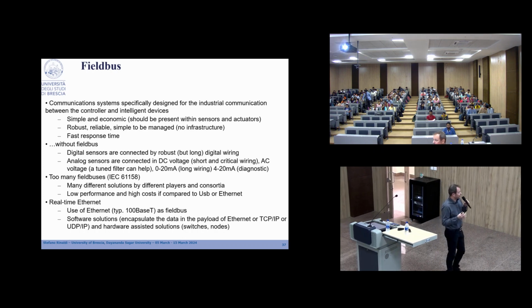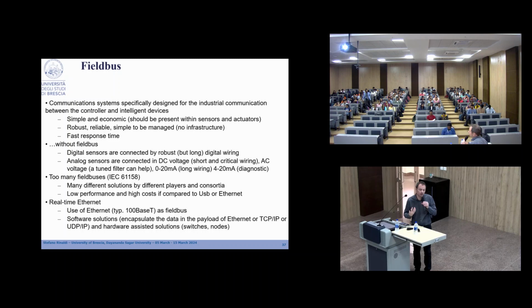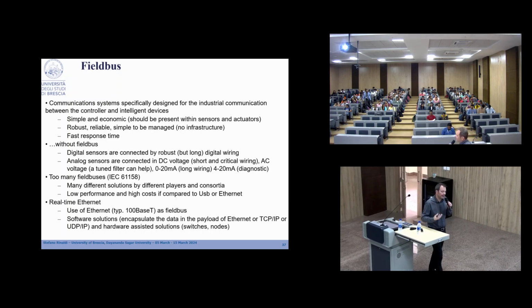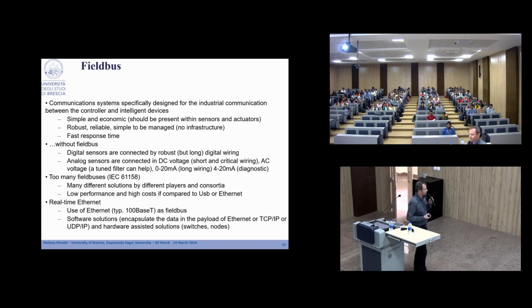In particular, the field bus should be simple and economic, because we need to reduce the cost of the installation of field buses in industrial plants, because a field bus can connect hundreds of sensors and hundreds of actuators in a real system. So it's important to reduce the cost of this communication.